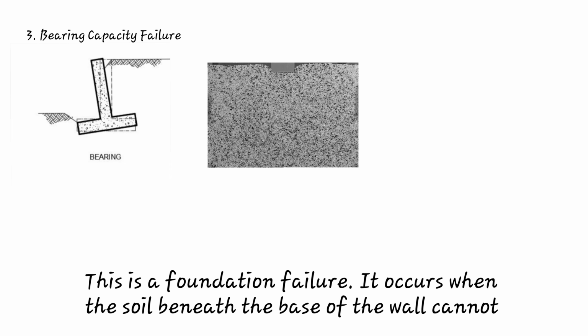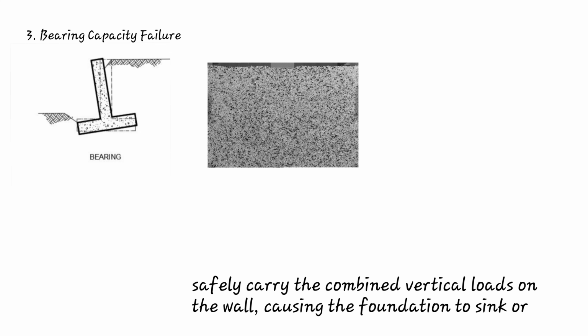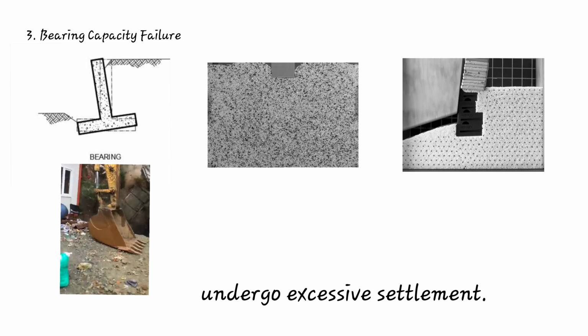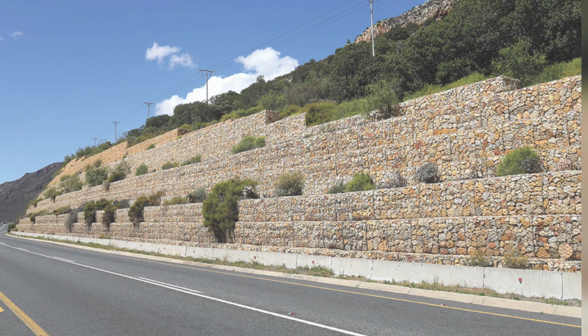3. Bearing capacity failure. This is a foundation failure. It occurs when the soil beneath the base of the wall cannot safely carry the combined vertical loads on the wall, causing the foundation to sink or undergo excessive settlement.